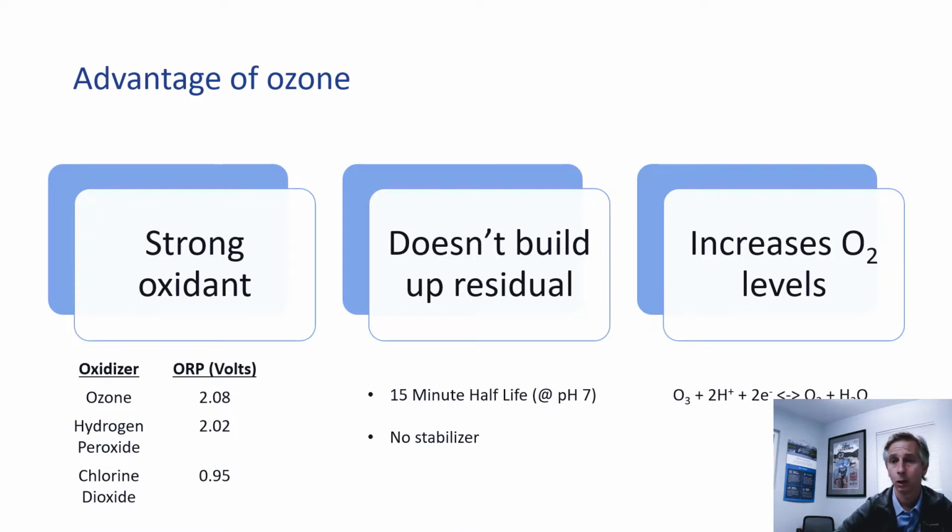Right, so a lower dosage of ozone with a contact time of about 15 minutes in the irrigation cycle will allow for proper control of bacteria and some unwanted yeast and molds like Fusarium and Pythium.